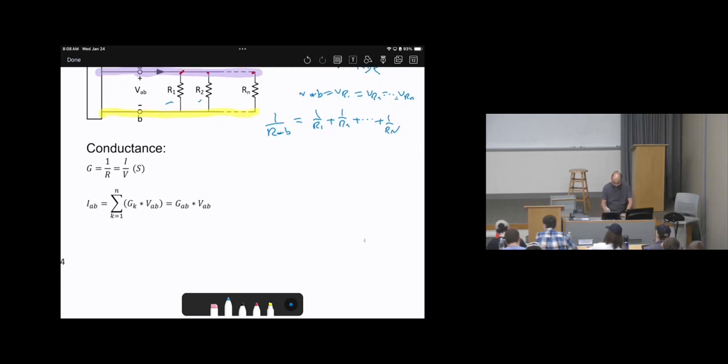Now, I'm going to write this example. Here we have R1, here we have R2, and here this is AB. Now, are those in series or in parallel? The best thing to determine this is to label the nodes. This is a node, and this is a node. So we will say R1 between the yellow and purple, R2 between yellow and purple. Therefore, they are sharing 2 nodes, right? Common in 2 nodes. Since they are common in 2 nodes, this means they are in parallel, right?